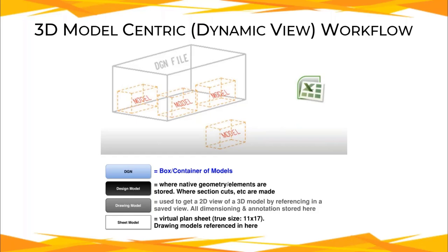And in a minute here, I'm going to show a chart in a couple slides that goes over design models, drawing models, and sheet models. But again, just to reiterate, design model is going to be that black background. That's where the native geometry and elements are stored, where we use section cuts or different tools to produce the views.